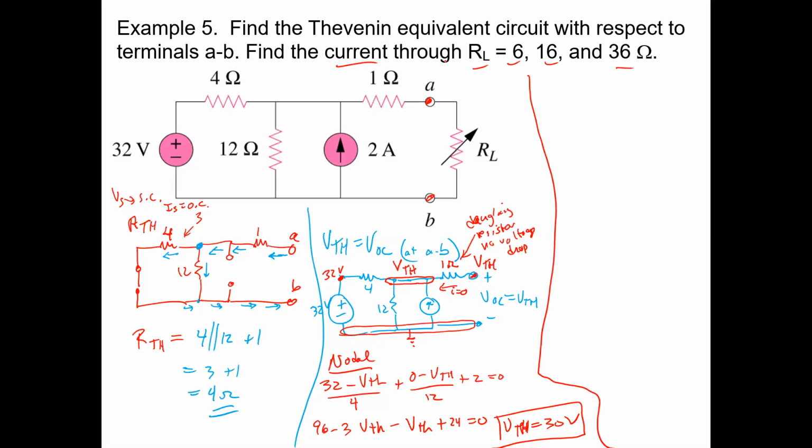This is the challenge with Thevenin: there are a few different approaches under different circumstances. We're going to be looking at the standard way, which is this way. When you just have independent sources, you can turn them all off and then measure the equivalent resistance. That's pretty easy to find R Thevenin. And then V Thevenin is just finding that open circuit voltage, which is usually easier using nodal analysis.